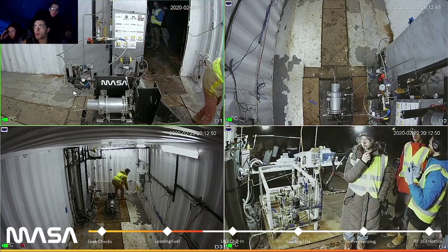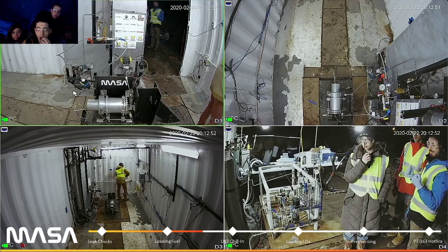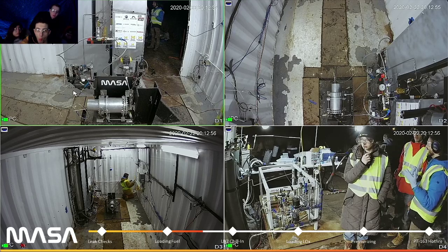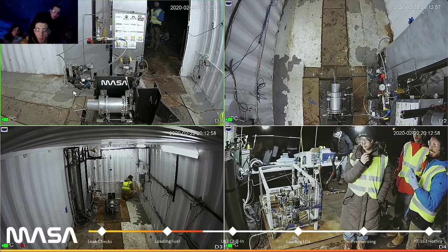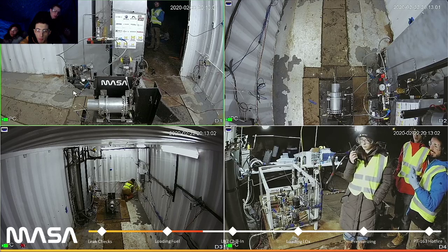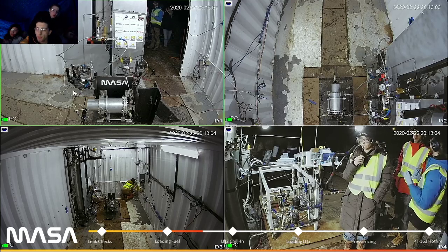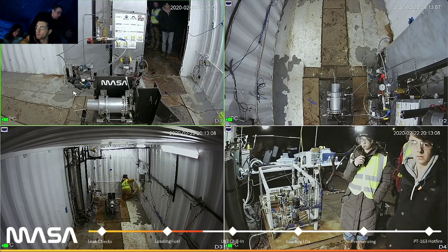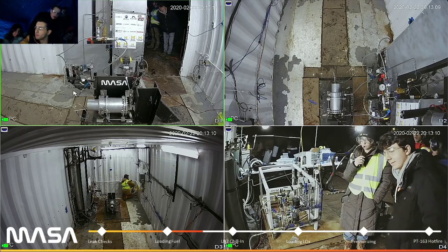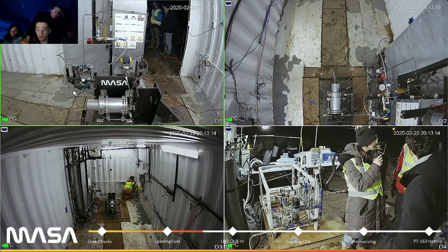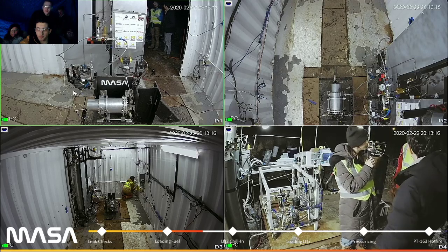TC asks, how did you plan it, unlike doublets, triplets? They're talking about the injector. For PT-163, we actually use unlike triplets, so it's going to be one oxidizer with 2 fuels impinging. We decided to switch that up for several design considerations that I won't get too far into right now. But for RPD2, we're going to be using doublets.